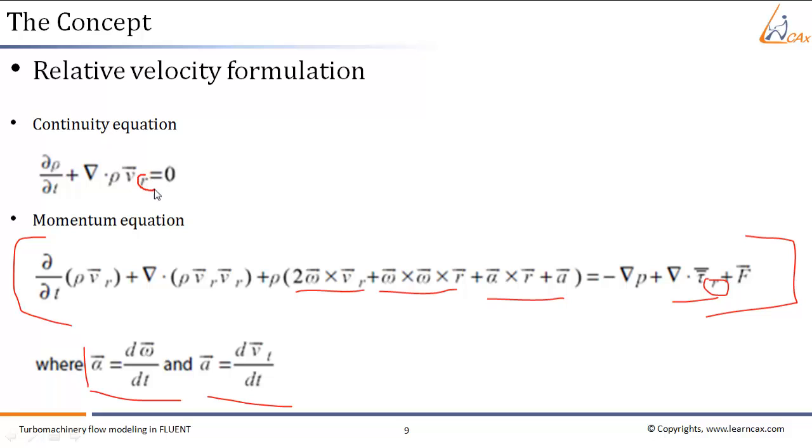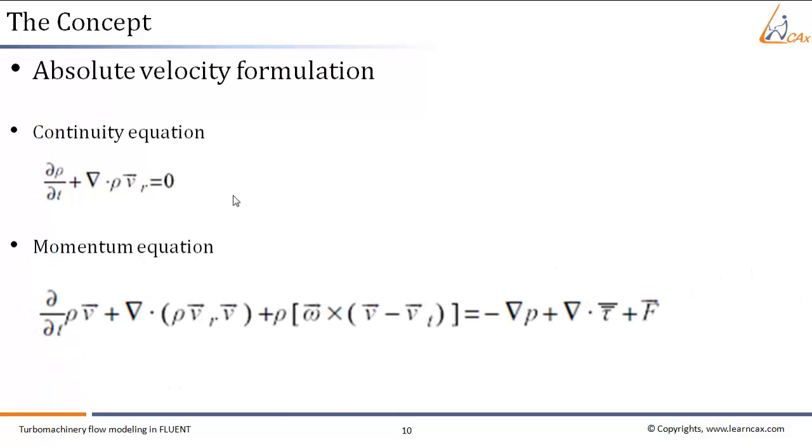Continuity equation is also written in terms of relative velocity. Now we come to the absolute velocity formulation. In the absolute velocity formulation, the governing equation of fluid flow for steadily moving reference frame is shown here. This is the continuity equation, this is the momentum equation.